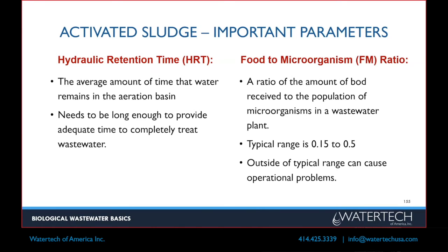Hydraulic retention time is how much time a given gallon of water spends in your system. It's really nice to have 24 hours of retention time. We have a customer, one of the ones I had up here, that's about 12. The longer you have, the more consistent you can be, and the longer your bacteria has to treat the water, the better. If it's too short, it's really hard to completely treat everything. Then there's the idea of food to microorganism ratio, F to M: basically how much COD, BOD you have coming in relative to how much bacteria you have. Again, it's one of those parameters you have to keep in balance to keep a healthy system.